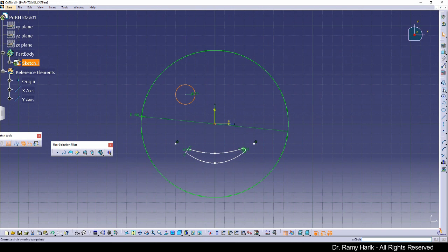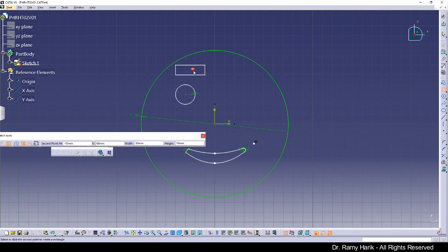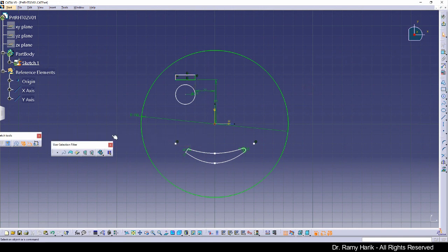Then we're going to click on a rectangular icon. And then we are going to enter from minus 40, 50 and to minus 20, 45. So in case you cannot select the other point because of the constraint, you can remove this one here to get it closer to it. So we wanted minus 20 and 45. So something that's almost similar to this. Now I'm going to click on my tab. So we said minus 20, 45, and we are done with this.